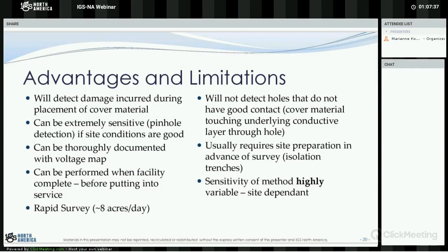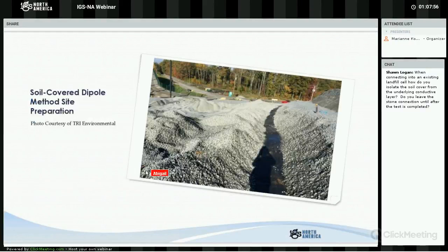You can come into a site and easily find that hole on day one, and then it rains overnight and it fills the perimeter up with water, and all of a sudden you have current flowing out the edges, and the next day you come and you can't see that 1/4 inch diameter leak. And sometimes we have to wait until that perimeter isolation actually dries out.